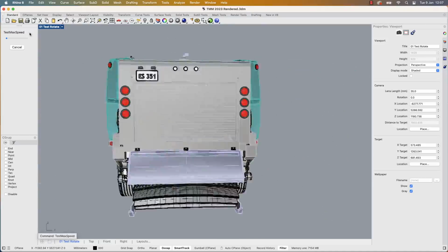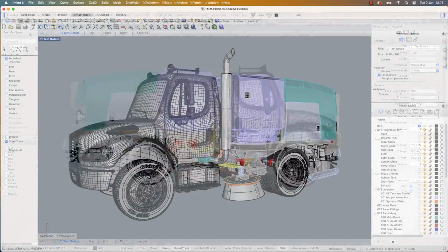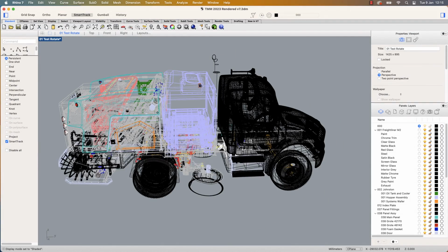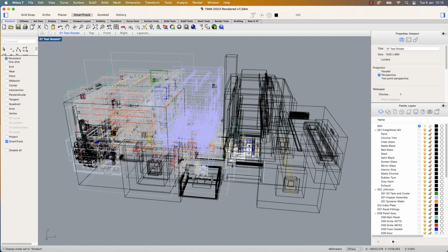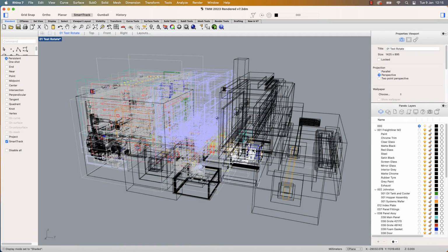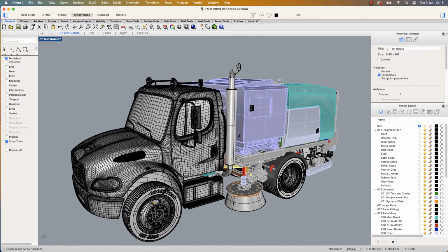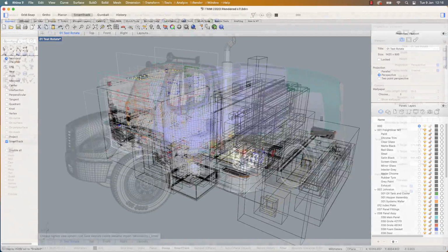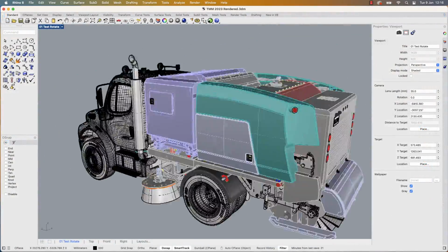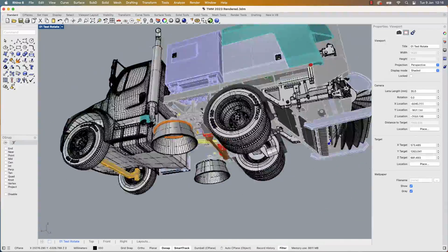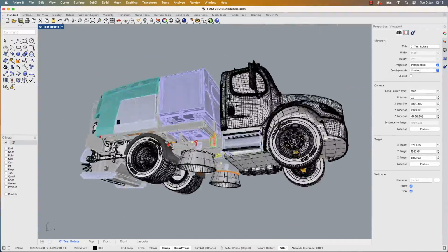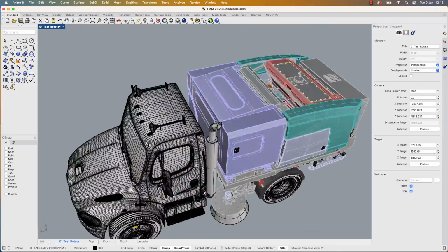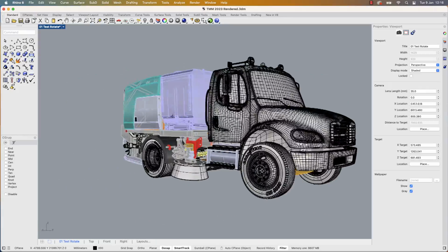Of course, test results don't paint the whole picture. Working with the model, zooming, changing the view angle, etc. causes real problems in Rhino 7, as we can see here. Parts of the model drop out and the mouse response is very delayed. This is, of course, due to the lack of any hardware support for OpenGL. Working on the same model in Rhino 8 with the Metal display pipeline leads to very smooth results. There's no dropouts or stuttering, and the overall feel, mouse feedback and performance is comparable to a high-end Windows solution.